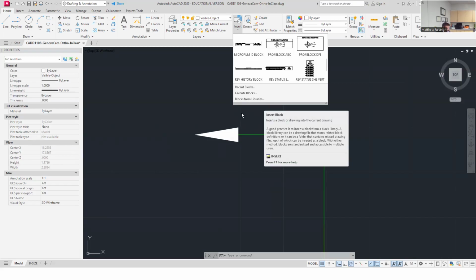If that arrow gets big, if for whatever reason, when I scale my drawing, the arrow adjusts and it may show the line type if it's a different line type. So object just has a continuous line type and it's kind of a heavier line weight. I think it's 0.4 millimeters. So I think that's just what I like to use. I can't say ASME has a standard on those or not, but the size they are. I just don't know what layer they want. I think they just want it as kind of a normal bold, not a light line, but just a dark line. So mine is a visible object layer.